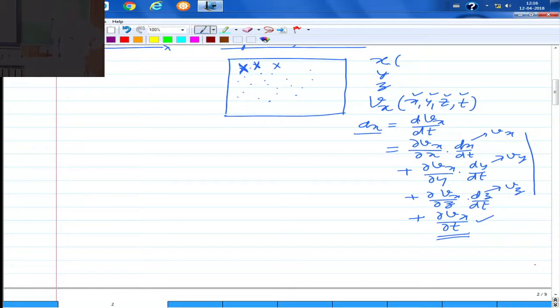The reason is that once the material point goes here, the boundaries of the control volume are fixed. While some material point enters here, after some time it occupies different locations within the control volume and then goes out. You are not tracing that. You are all the time studying, for a material point at this particular location, what its velocity, acceleration, stresses, or strain rates are. So you find that these derivative terms are additionally there in the Eulerian description of motion.